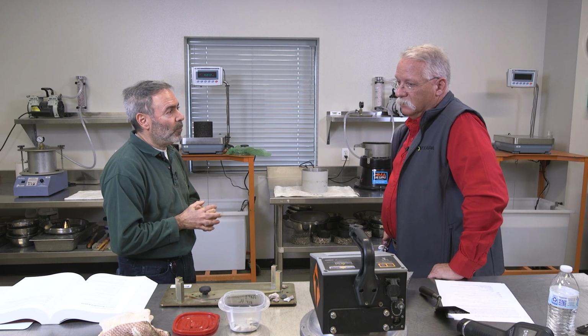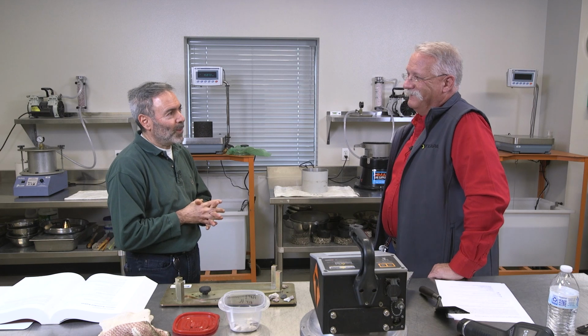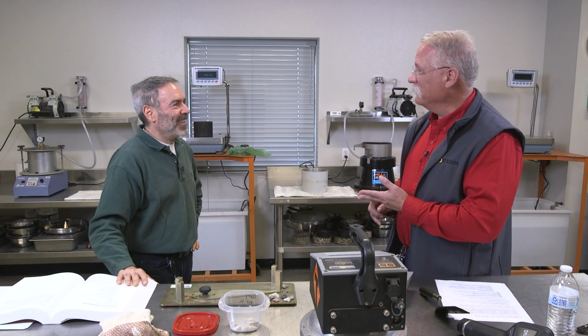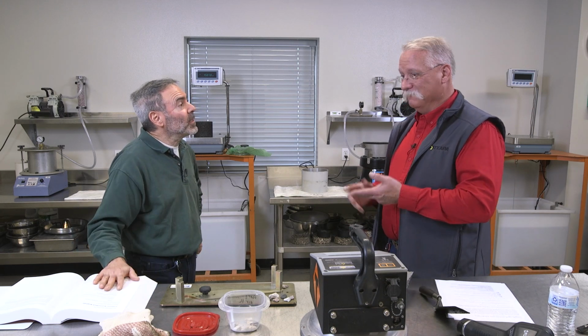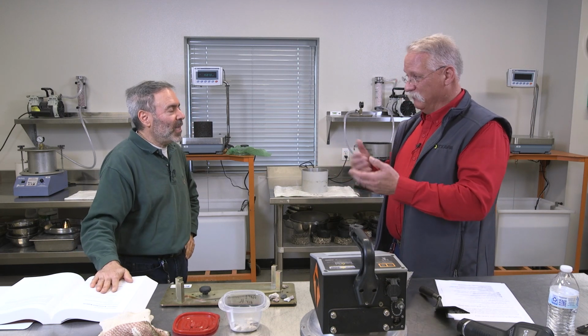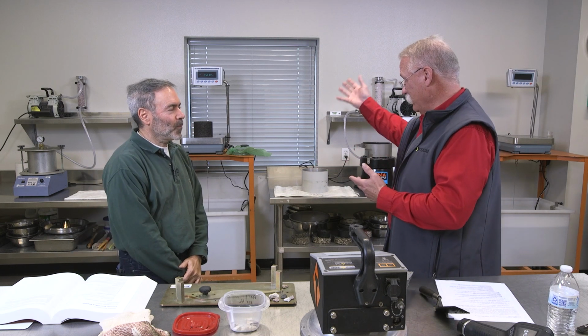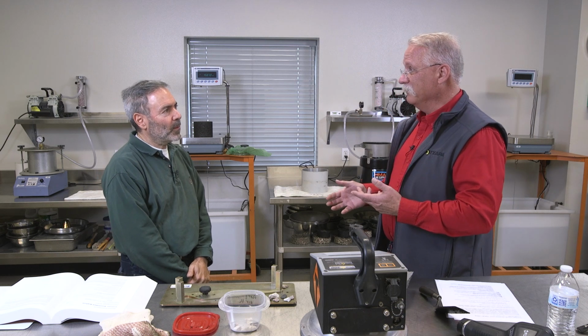Do QC and QA use the same test procedure? Yes, such as asphalt content and gradation. If we're going to compare, we've both got to be certified. We both got to be using appropriate equipment, and we got to follow the procedures.